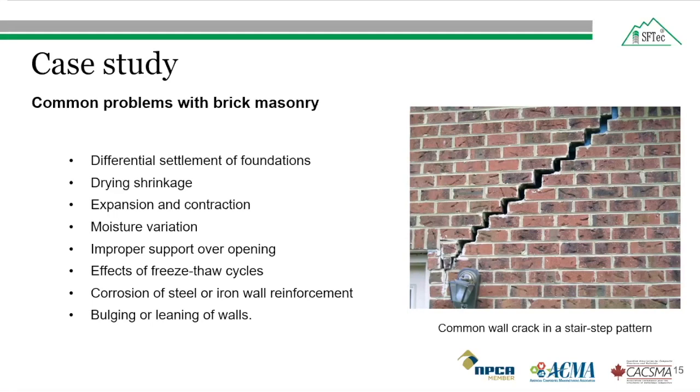So above ground brick walls expand in warm weather and contract in cool weather, which develops stress in the walls that may cause a variety of cracking patterns depending on the configuration of the wall and the number and location of the windows and doors. Such cracks, which are shown in the figure, are normally reoccurring and will open and close with the season. They will grow wider in the cold weather and narrower in the hot weather. Active cracks must be sealed and inactive cracks may be pointed.